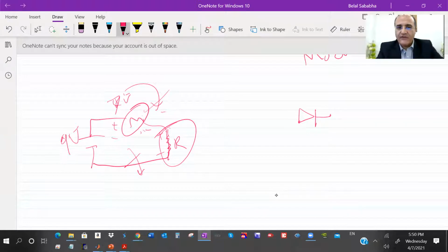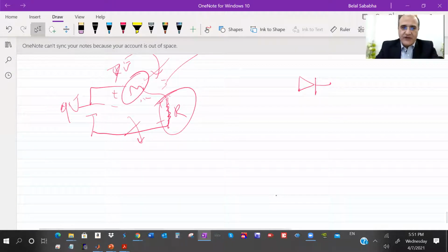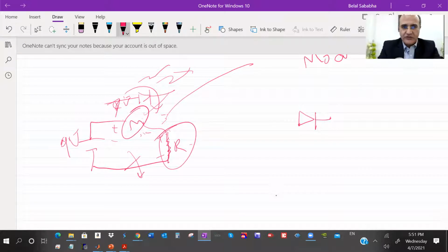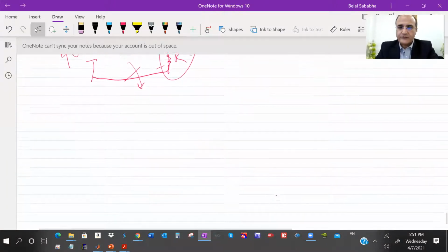So you will not have the full range of speed from minimum to maximum, from 1 RPM to 1000 RPM. After 7 volts it will work and give you some RPM until the maximum, not the whole range. Same here: if you replace the motor with an LED, changing this will change the brightness, right?